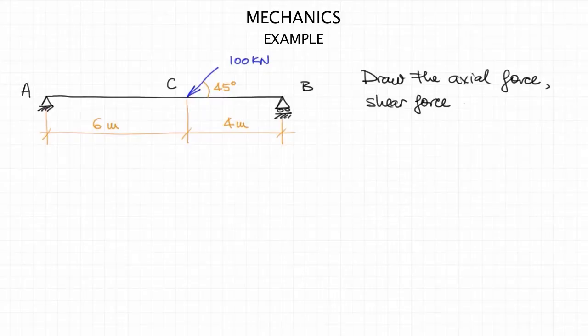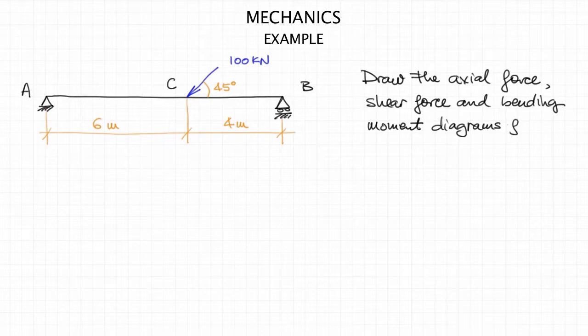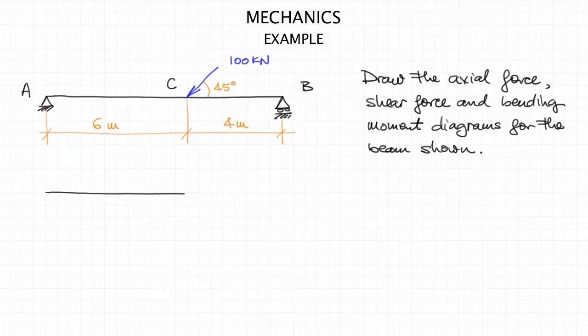What we need to do is draw the internal force diagrams for this beam, so hence the axial force, shear force, and bending moment diagrams. You should know that whenever there are forces that have components directed along the beam, then probably there will be an axial force internal to the beam, so then you'd have to draw that diagram as well.